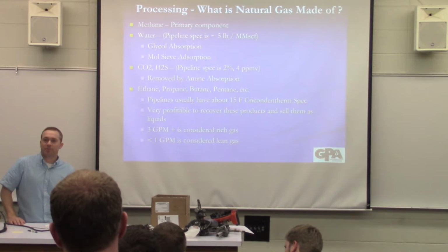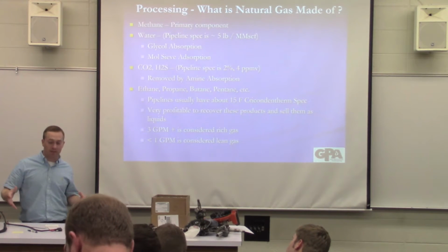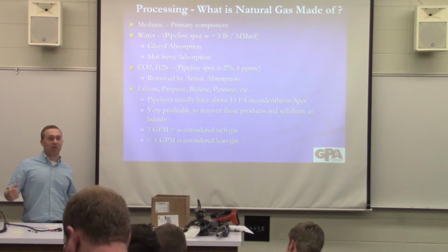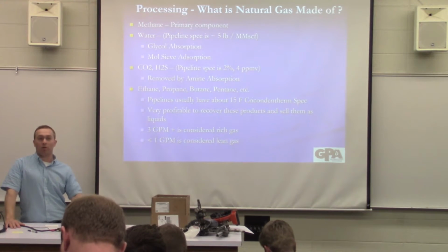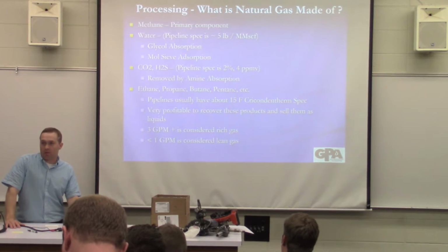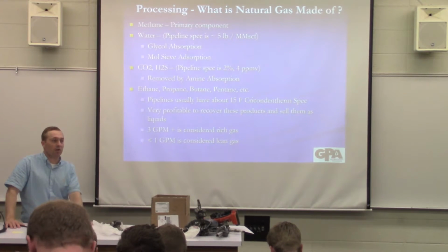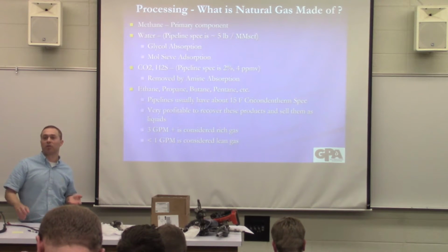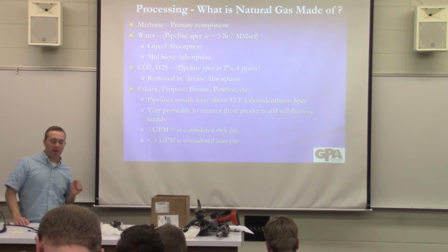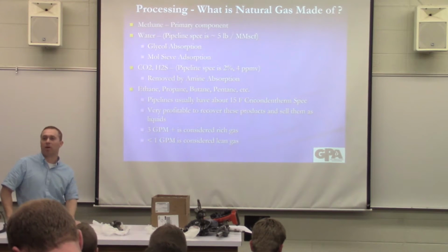Yeah. There's a lot of energy for. Yeah, so it's dangerous in the sense that we process these in a gas processing plant, but also if these are traveling through a pipeline and they might go over a range of pressures, and could be some natural cooling that takes place as they're being transported underground, some of these components would naturally fall out, and you don't want any liquid hydrocarbons going to your appliance.